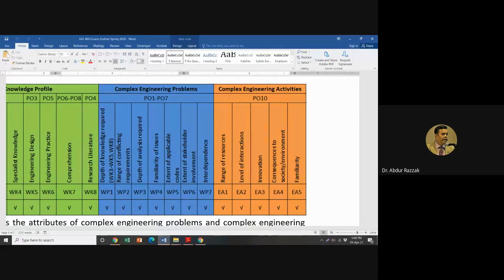You see that yes, there is output in the 2nd stage. So what is the problem? The problem is between the 2nd and 3rd stage. Then disconnect the 3rd and 4th, and give the output of the 2nd stage to the 3rd stage, and just check whether the 3rd stage is working. You just troubleshoot. So this is the interaction.